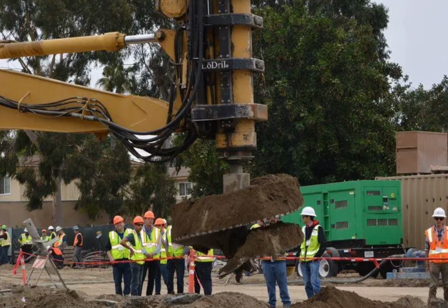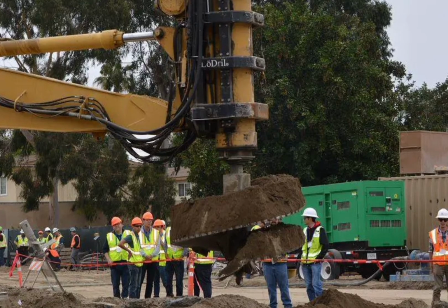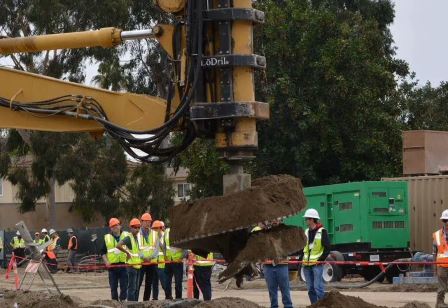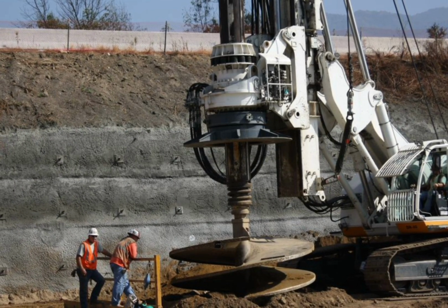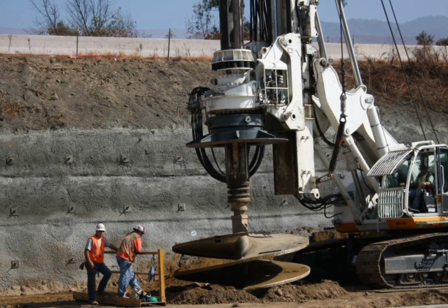We do this for 3 or 4 samples under different normal loads. By plotting the shear stress at failure against the normal stress for each test, we get a straight line. The intercept of this line is the cohesion, and the slope is the friction angle. This test is great for sandy and gravelly soils, but it has a limitation. The failure plane is forced, which isn't always how soil fails in reality.